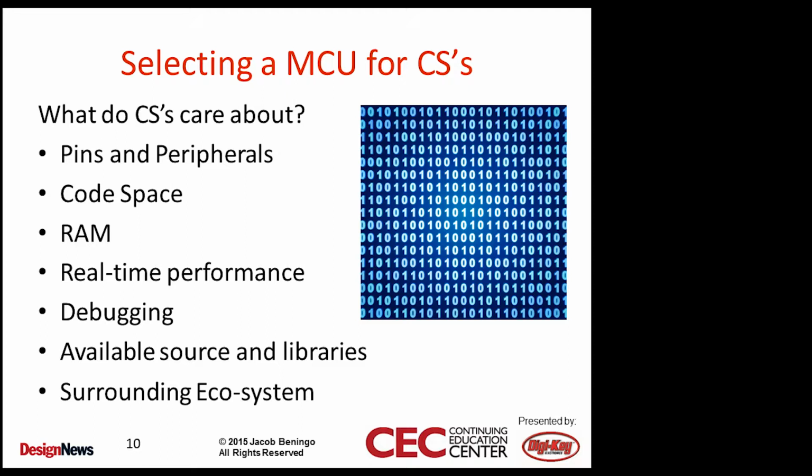Now, that might mean that a computer scientist is going to want more pins available so that they can do debugging and some optimization with the actual software they're writing. Whereas the electrical engineer is going to say, hey, I want to try to minimize my pin count, and I'm basically going to just have pins assigned to things that need to go to other chips or that are actually needed. They're generally not going to design in those extra pins for a software guy unless you request them, saying, hey, can you leave me 4 extra pins so that I can do some performance measurements? In which case they might look at a different package or do some additional trade-offs to get you those so that you can perform timing measurements on your code.